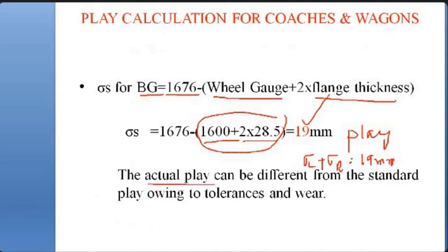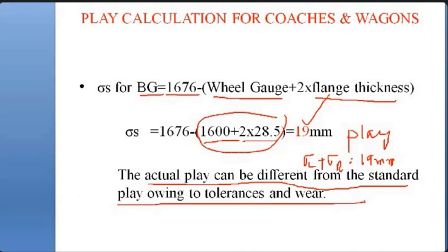Here I told you one more thing. The actual play can be different from the standard play owing to tolerances and other wear of the rail and wear of the flange. So all these things also influence it. I hope it is clear to you. What is play? Understood or not? This play is very, very important.